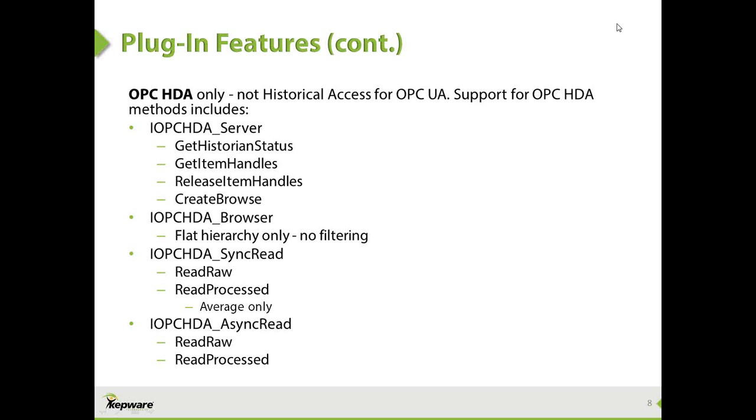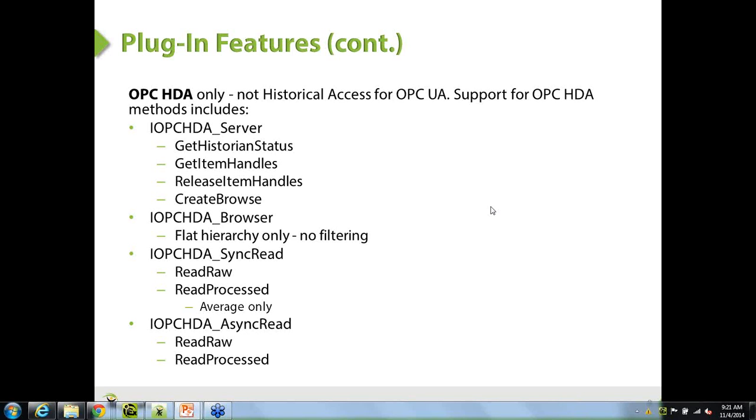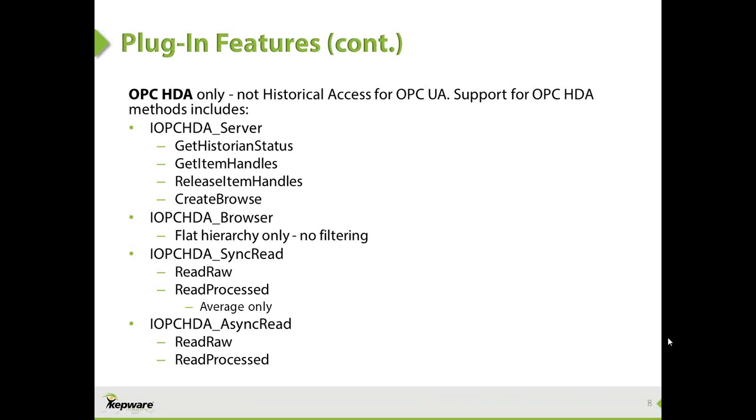The plugin uses the classic specification for OPC HDA. The plugin has passed the OPC Foundation's Certification Test Tool for HDA self-compliance, and we've also tested this with numerous third-party HDA clients. It displays all those raw values from the data store for validation, but we do not include visualization, trending, reporting, or analytics. That would be done by some HDA client software that you might have.